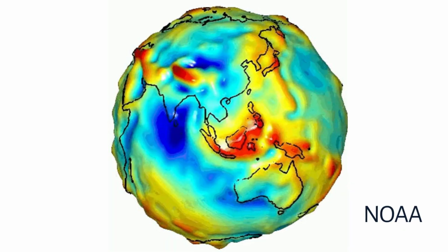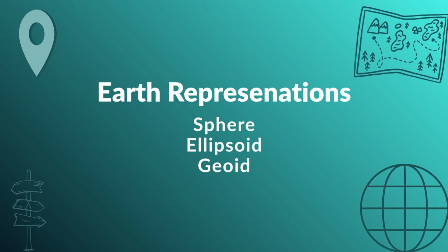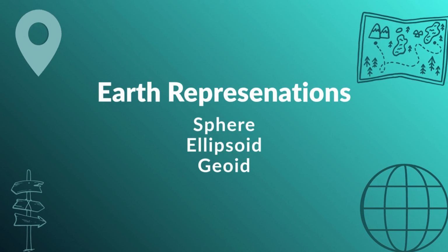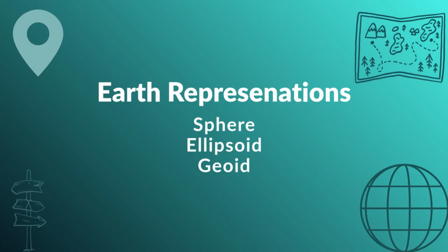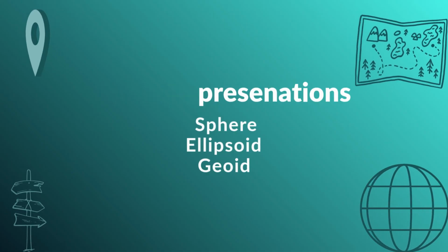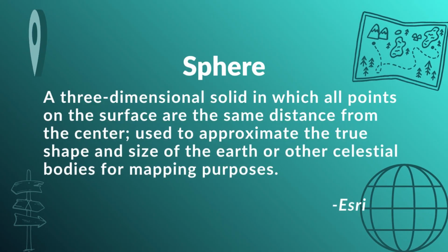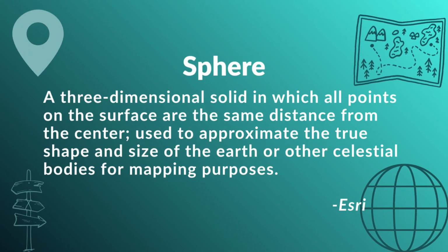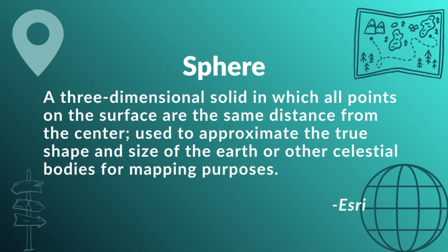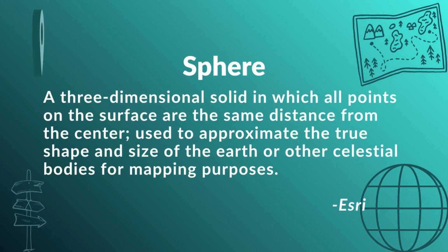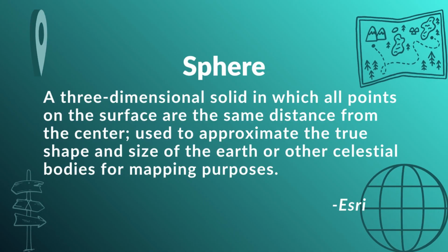Well, let's start right there with the actual shape of the Earth. If we want to assign a coordinate to a physical location, we first have to define the canvas we're working on, right? For the GISP exam, there are 3 primary models of Earth geometry that you must be able to differentiate: the sphere, the ellipsoid, and the geoid. The sphere is obviously the most basic, a perfectly 3D round shape with a constant radius everywhere. But in professional GIS, a purely spherical model is rarely used for high-precision analysis. Almost never. It's computationally lightweight, so it gets used for very simplified, small-scale web globe rendering, places where speed is prioritized over actual geodetic accuracy.